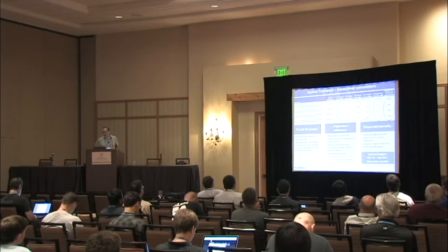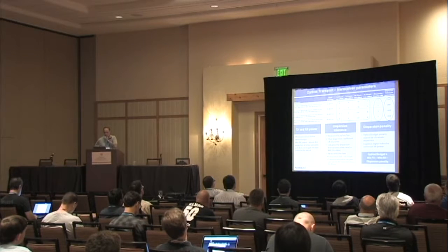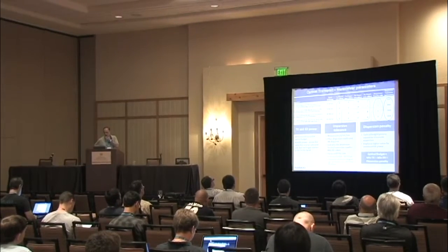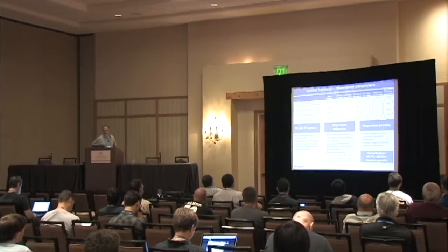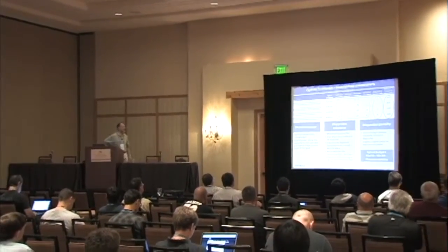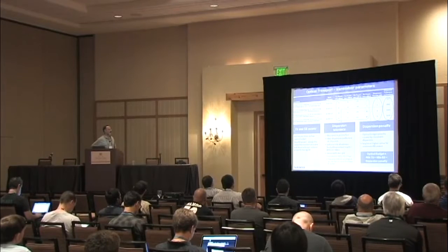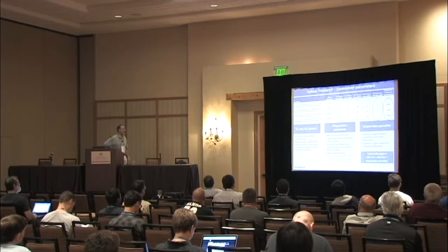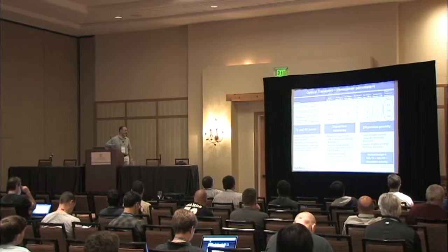Now, having in the red circle the dispersion tolerance. Dispersion tolerance basically defines the dispersion-limited transceiver reach. It's measured in ps per nanometer per kilometer. And every type of fiber has a fiber dispersion coefficient. The standard SMF28 fiber generally has a coefficient of 17 or 18 to 20 ps per nanometer. And having a dispersion tolerance of 800 divided by 20 leads us to the 40 kilometer theoretical reach.